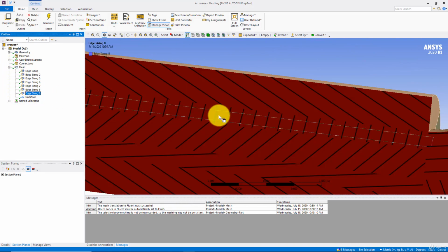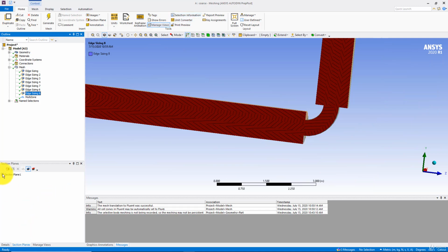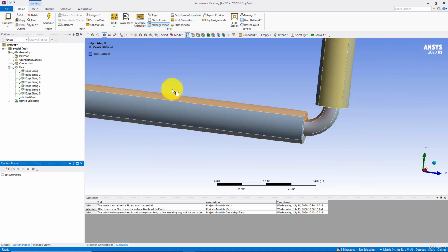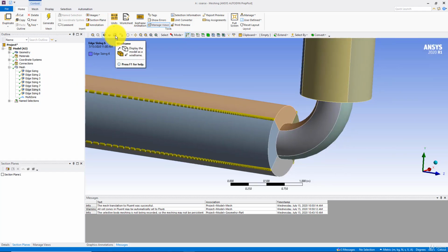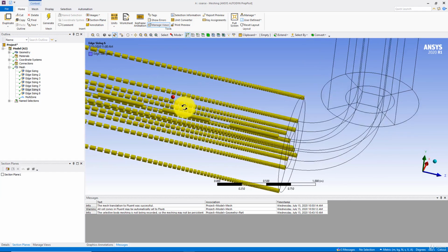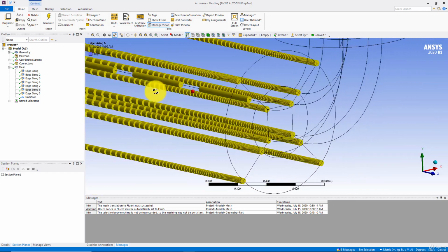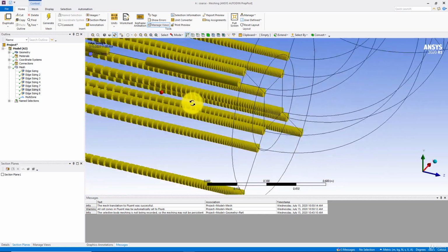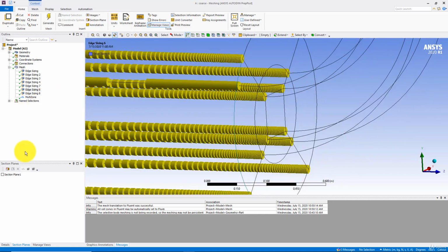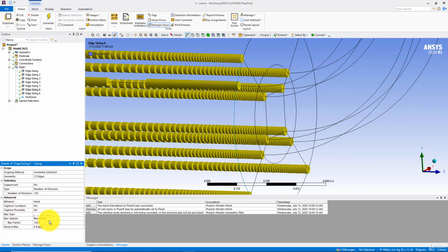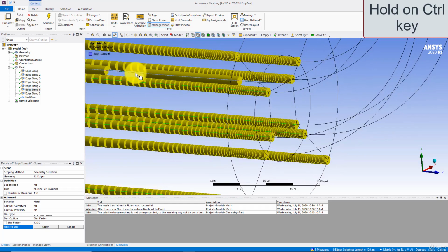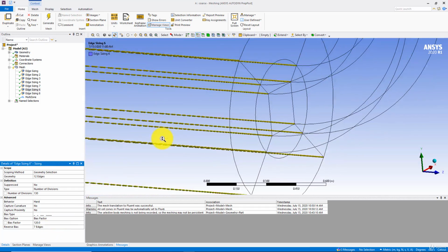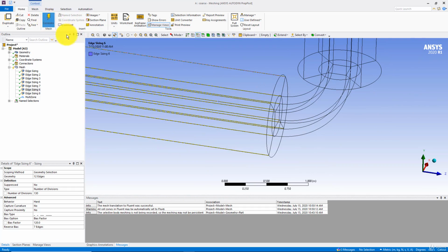We have to go to edge sizing and also turn off the section planes. And from the edge sizing, we have to look for the edge sizing for these edges, and in the wireframe mode first, I can see the problem edge. This is the problem edge here. And we have to turn on the reverse biasing for this edge from details. So just highlight this edge and apply. And now again click on generate.